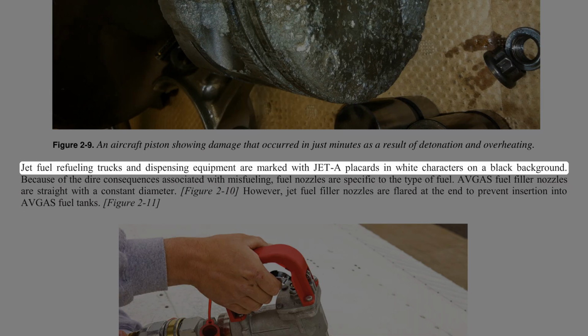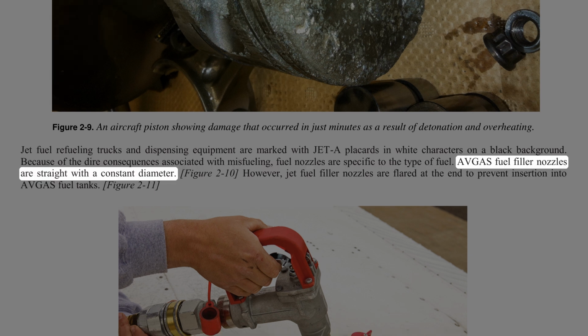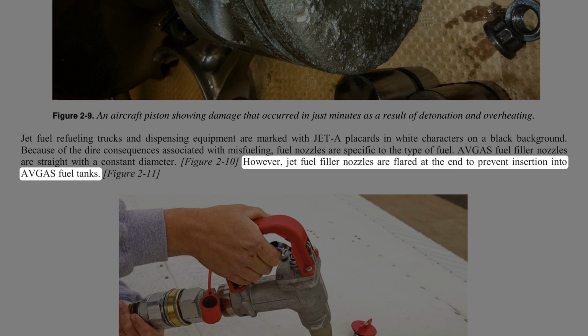Jet fuel refueling trucks and dispensing equipment are marked with JET A placards in white characters on a black background. Because of the dire consequences associated with misfueling, fuel nozzles are specific to the type of fuel. Avgas fuel filler nozzles are straight with a constant diameter. However, jet fuel filler nozzles are flared at the end to prevent insertion into avgas fuel tanks.